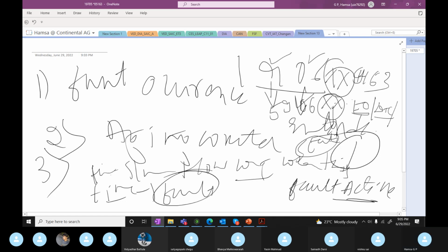I'll explain the aging counter when I explain the 14 service, and you will understand easily then. So just remember the name aging counter. It talks about how old the fault is in the system. And as we discussed, how much time the system took to set this fault, and how long the system is running when the fault is in active state. These are all the more information about one fault, which we will get on 1906. Clear?